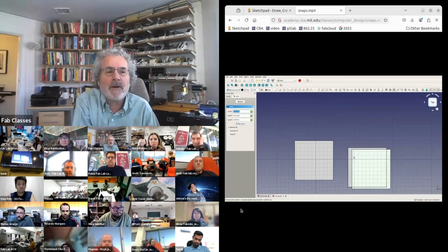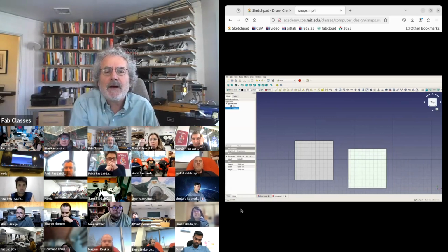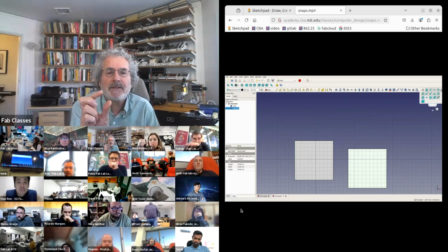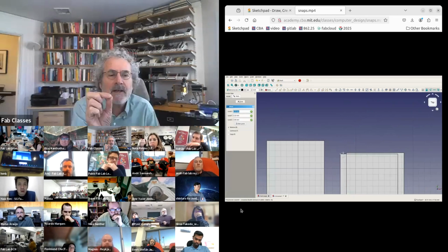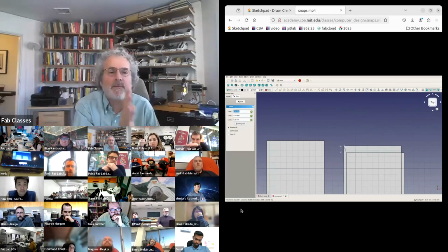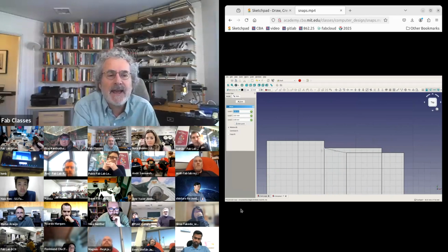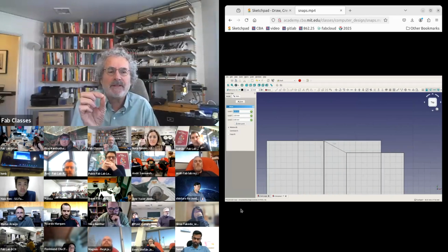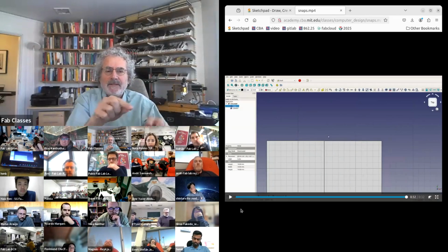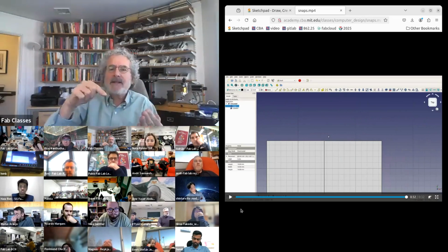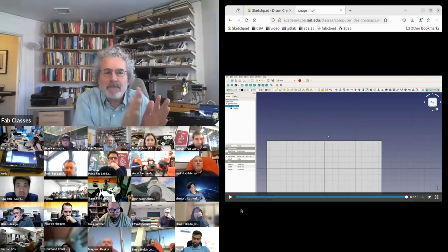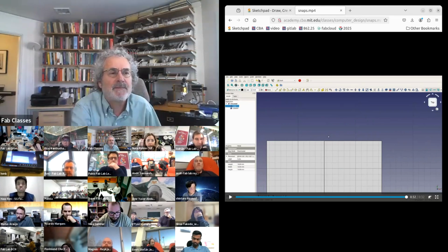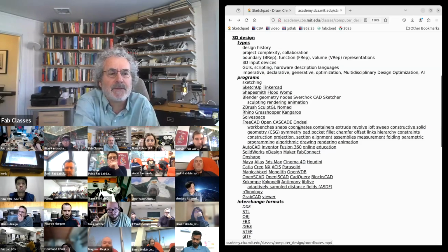Right now I can move a part wherever I want. These are all different snaps. One snap says I should only move in steps of the grid. With that one turned on, right now I'm showing a snap that only moves horizontally or vertically. Here's a snap that says I have to move to grid points. That was a snap that says vertices touch. I showed you a snap that shows edges touch. All of these help you place parts by forcing alignment. So those are turning on and off various snaps.